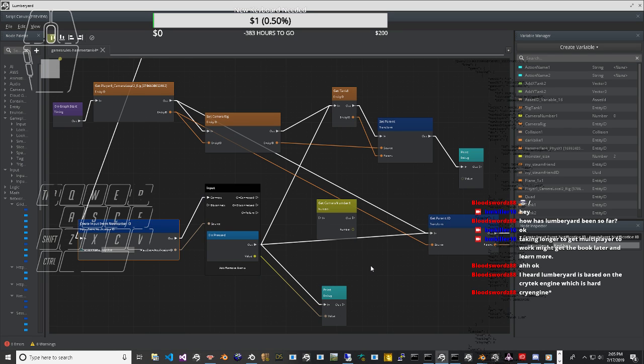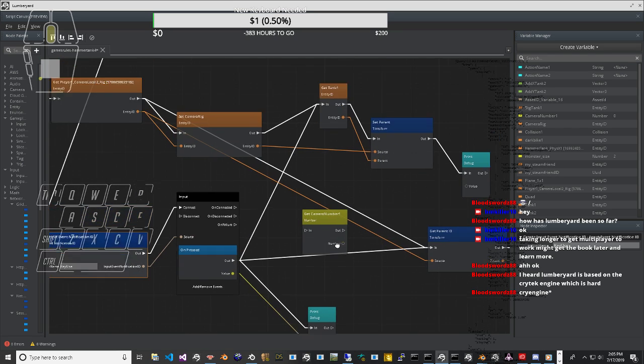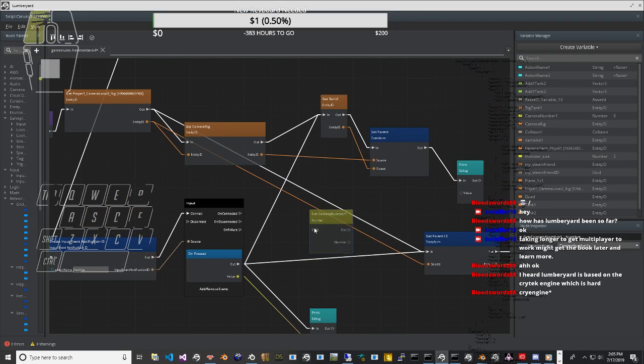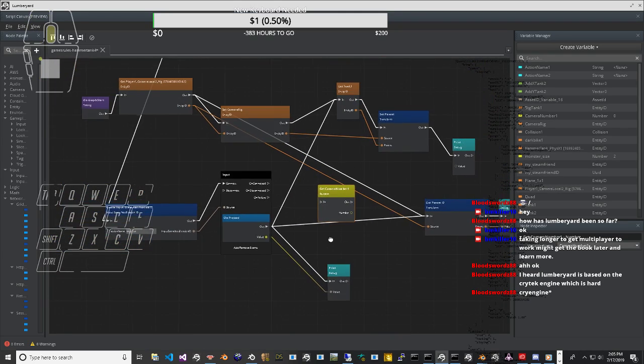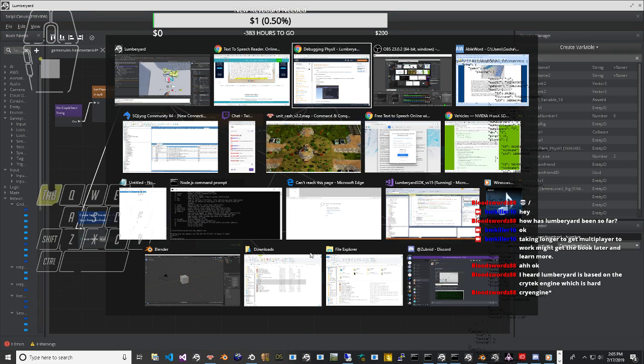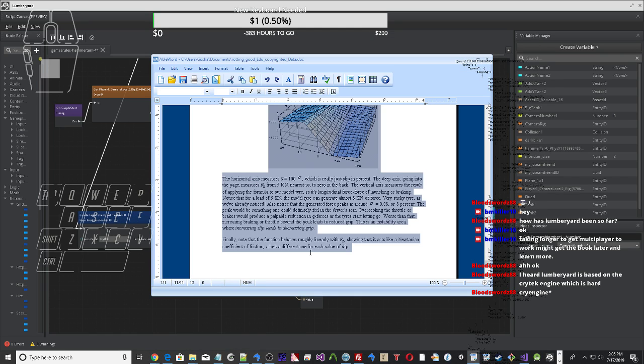Longitudinal slip is along the mean plane of the wheel and might also be called circumferential or tangential. It creates braking and accelerating forces. Lateral slip is our old friend slip angle, which tells us how it generates cornering forces.